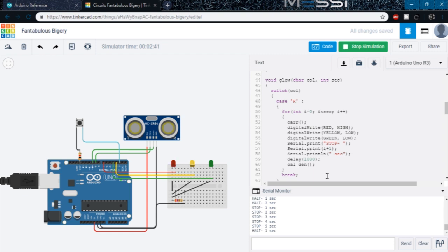This is a point to be noted, guys. When we are using delay, it is actually a single line function. It will not increase anything. I mean, you can use whatever you want in the delay, but when you are using millis, it will take quite a lot of space and lines. And here what we can do rather than millis is use an interrupt. Now what the heck is that?